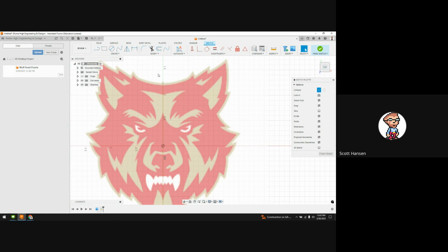Now, there are drawing tools out there that will trace drawings like this for you. But for our purposes, if we're doing this strictly in Autodesk Fusion, if you're tracing an existing raster image like this image that I downloaded here, you might have to use some of these drawing tools to trace things manually. So yeah, this little piece right here looks kind of like an arc to me. Oop, let me turn my construction tool off. So I'm going to draw an arc. Let me grab the line tool, make a little line going down here. These look like just lines, so easy enough to draw those. Looks like I need another arc.